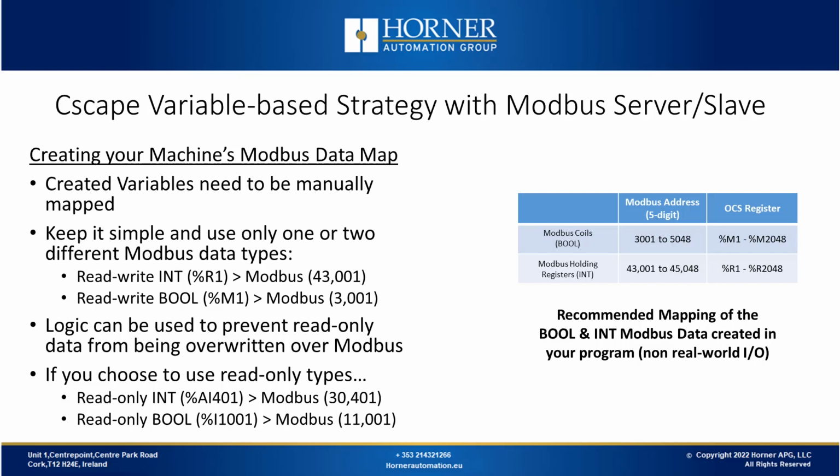Similarly, with an integer or longer type value, if you want that to be read-only and you don't want that to be overwritten, then by using a move function or another function that's continuously writing that value in your program, it'll prevent Modbus from overwriting it. By doing that, you'll eliminate the need to use input registers or input bits.